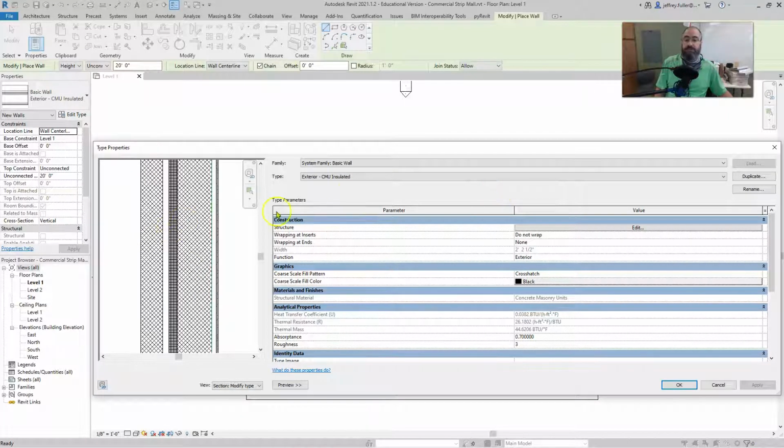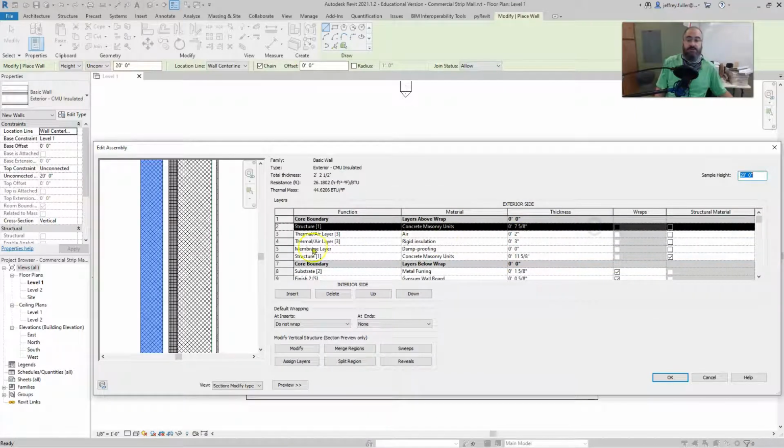And let's see how they got this one structured. Okay, so the concrete masonry units are on the outside. It's some type of block, not necessarily a cinder block. These are only 7 5/8 inches thick. And it's probably not like the big type of blocks that have the hollow core, but this is probably more like a solid block.